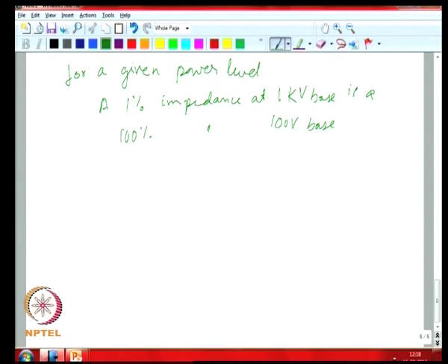Okay. So, as one goes up to higher voltage levels, similar impedance will appear actually much smaller. So, if you look at your transmission system, your voltage levels tend to be very high. So, looking at it from the load side, you can actually get closer to the assumption that your grid is getting more and more ideal when you are looking back into the system. Okay.